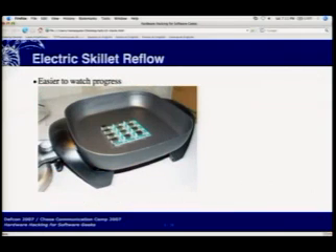Skillet reflow, same trick. It's just for one-sided boards only. Works very well for surface mount, and is a whole $30 if you buy the skillet new in terms of parts investment, which is hard to beat. These pictures actually came from sparkfun.com, which is a site that has some fantastic tutorials on doing this and supplies a lot of the useful parts for this sort of trickery.